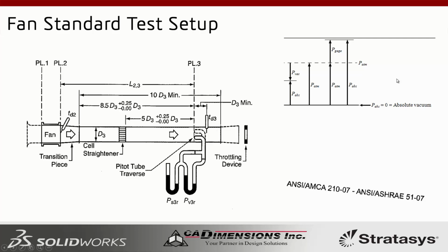In the real world, your pitot tube will be attached to some gauge calibration or a device that shows you what the pressure is in the system. This pressure is typically given to you as P gauge, so gauge pressure. So 1,000 or 2,000, that's gauge pressure. That is additional to the atmospheric pressure.